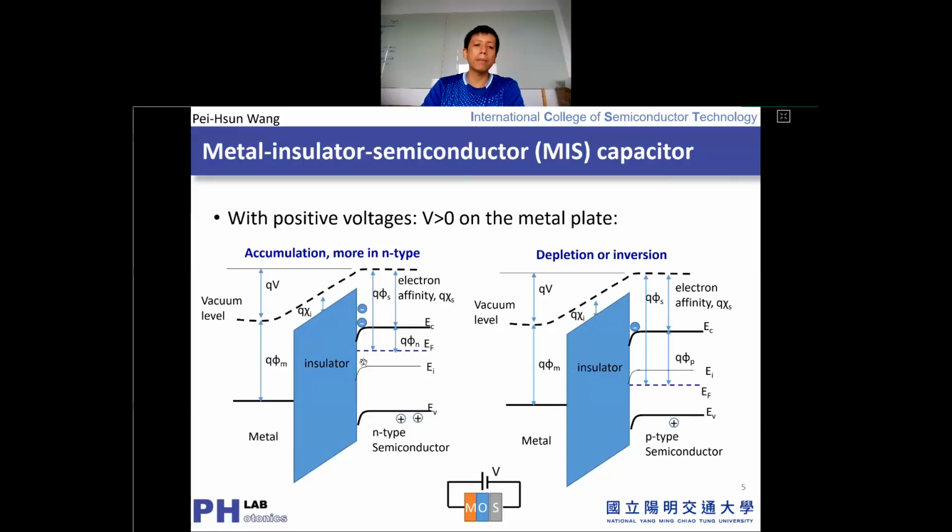So you can think what happened here is that we get the band bending. And then as we mentioned, these band bending structures will allow you to accumulate more electrons along the surface. The reason is because we get the band down, and the electron seems to be moved forward because we get the electric field from metal to semiconductor, from left to right. So when applying this left to right, you can see if you have any free electron from the semiconductor side, it will inject from right to left.